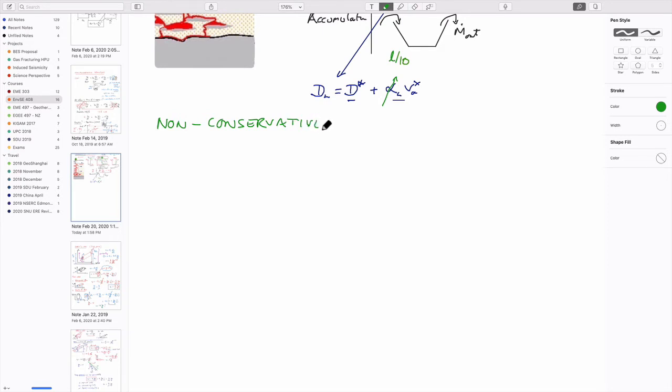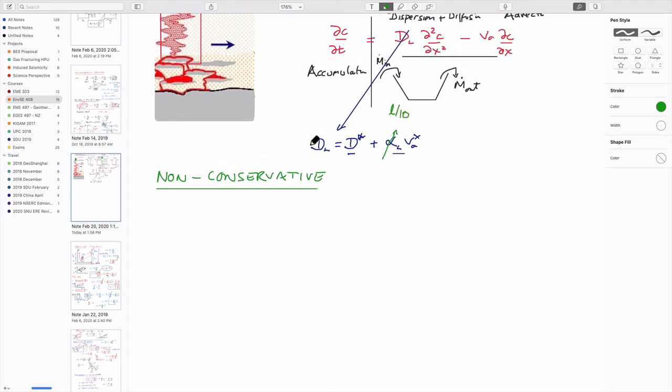And so the idea here, and it's especially true for these dissolved solvents, typically they don't attach themselves to quartz grains in sands, but if there is any organic carbon, in the same way that you can imagine putting these solvents dissolved in water through an activated carbon filter to take that out into the carbon, that is exactly the same process that will act in an aquifer that has not activated, but natural carbon sitting in it.